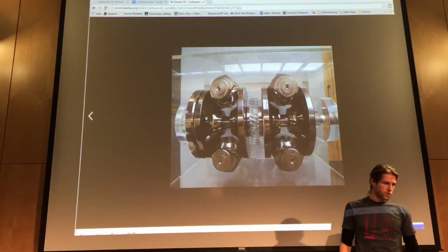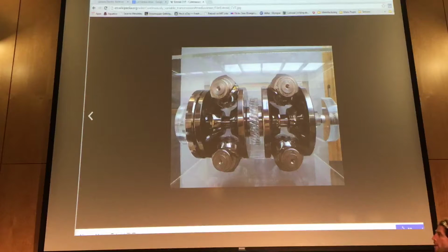And it turns out the reason you could want to do this is there's no backlash, so it's just friction. These faces are just touching each other. Whenever you have gear teeth, there's some gap in between them, and when they drive one direction, they come into contact. When you reverse the direction, there's a point when they're just moving through the air, and there's a smacking that happens. If you try to servo them, like you want to control the position, there's this little slop in the drivetrain that's called backlash, and that causes huge issues in control systems. So you're always trying to get rid of backlash in your drive system.